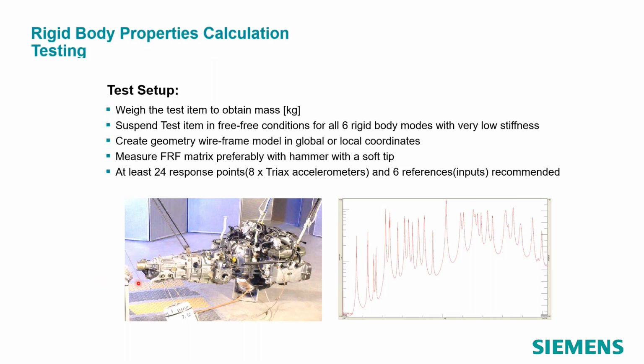You could see perhaps if I had a horizontal bungee, I could possibly be constraining it about a yaw mode here, or maybe if I had a bungee that was too stiff vertically going to the top and the floor, perhaps I'd be constraining that pitch mode. So when you pick your bungee locations, make sure you're not constraining it so it can't bounce about X, Y, or Z, and that you're not constraining it so it doesn't rotate about X, Y, or Z as well. You want to make sure it's free to translate and rotate in all 6 degrees of freedom.